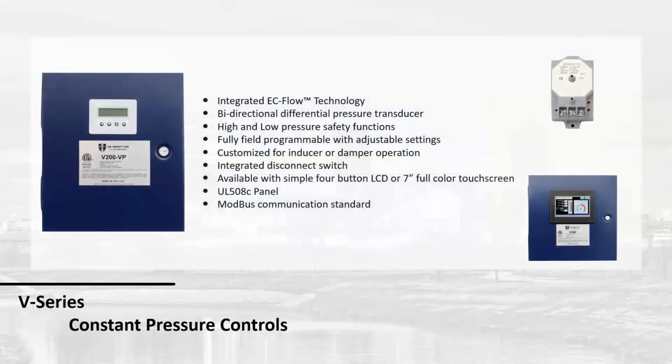And that's true of all of our V-Series controllers, starting with the baby one at 150 all the way up to the 350. They all have that EC flow technology, true bi-directional, positive and negative at the same time. There are some manufacturers that are coming out saying that they are also bi-directional, but what they've done is they've taken that 0 to 6/10 and they've just flipped it. So now they can read positive or negative. We can read across 0 with all of our controllers.